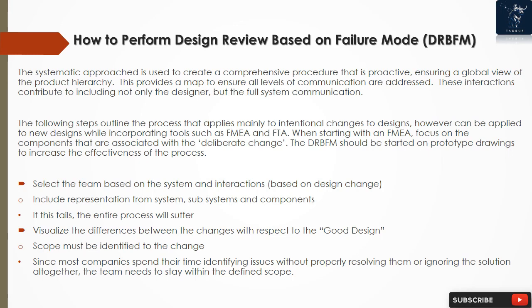The following steps outline the process that applies mainly to intentional changes to designs, however can be applied to new designs while incorporating tools such as FMEA and FTA. When starting with an FMEA, focus on the components that are associated with the deliberate change. The DRBFM should be started on prototype drawings to increase the effectiveness of the process.